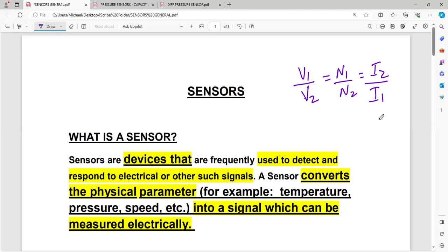So we are reducing that voltage from 440, or whatever voltage is supplied, and it is generally 440. You're reducing it to 24 volts. And by stepping down the voltage, you're increasing the current. And therefore, he'll get that entire range of current that is required to do the welding. Okay?